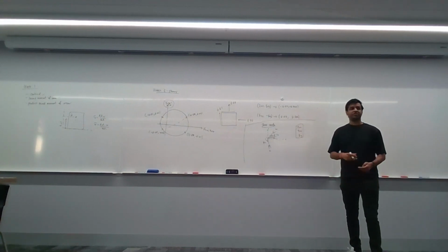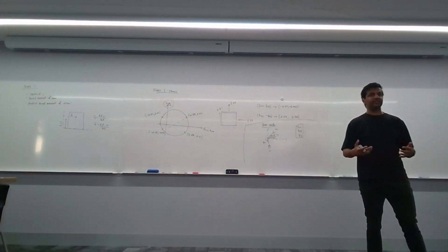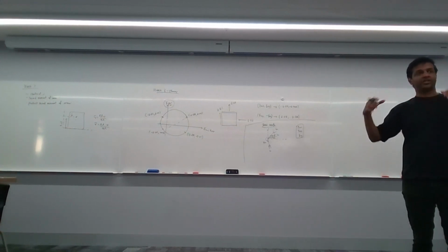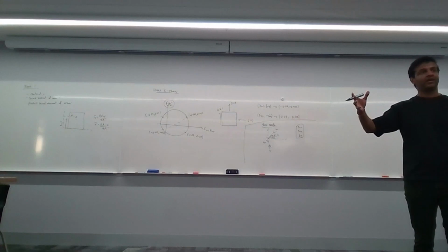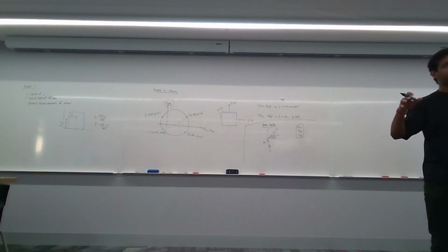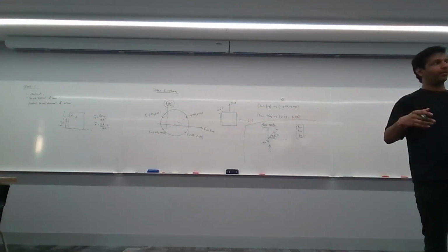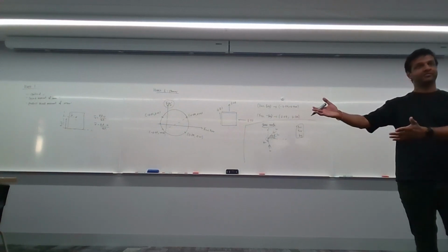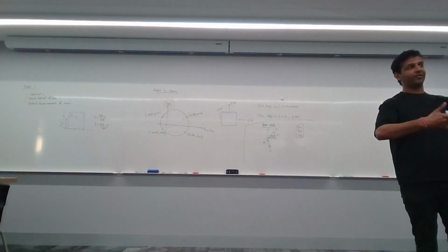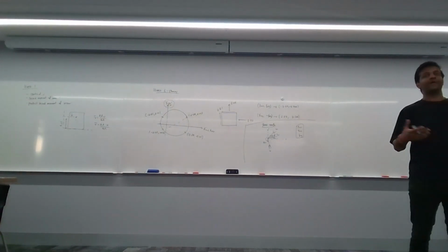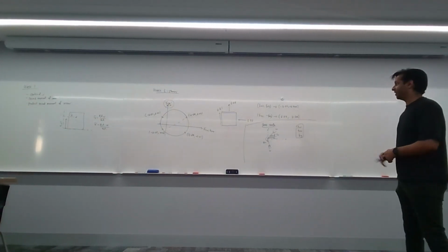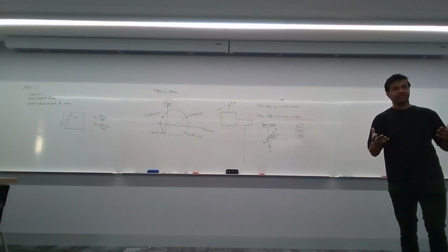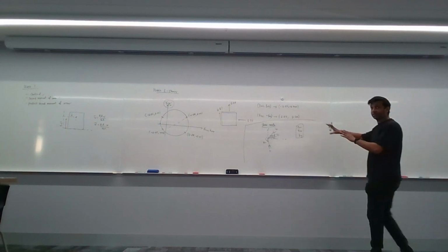Generally, the way you'll see strain rosette stuff in questions is as the first part of the question. They give you a combination of strain gauges pointed in different directions and ask you to calculate what epsilon xx, epsilon yy, and gamma xy are, and then after that they'll lead you into the Mohr circle stuff, or it can be Hooke's law stuff, however they wish. These tend to be compound type questions, and the strain rosette is generally the first part. It's not meant to be difficult, and it's not meant to be a trick. Just make sure you have those formulas with you.